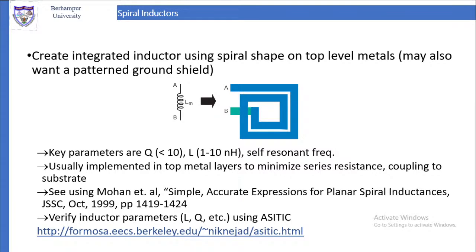Now in the chip, how do you realize inductance? The inductors that you see in the lab, or in the pictures in your books, are coils. Coils give you inductance, that we know. Now a coil is a 3D entity. When you are designing an integrated circuit, putting in a 3D inductor is out of the question. The chip is planar in nature.